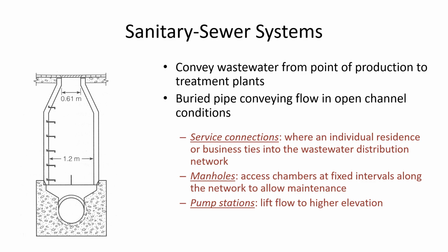The thing about water flow through these sewer pipes is that they lay them out on a relatively shallow angle because they don't want the pipes to be getting deeper and deeper, because, number one, it costs a lot of money to excavate a deep trench where they put the pipes in. But then the deeper the pipe gets, they're eventually going to have to lift the water up at the treatment plant or at intermediate pumping stations. And so by and large, unless you're in a city that's already steep, here in the floodplain part of Huntington, the sewer and storm sewer pipes are laid out relatively flat.